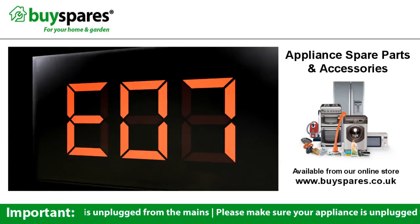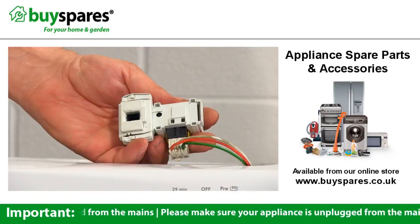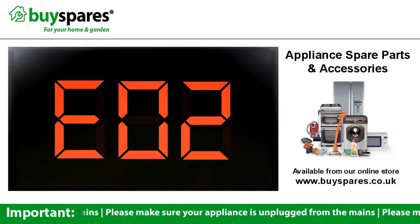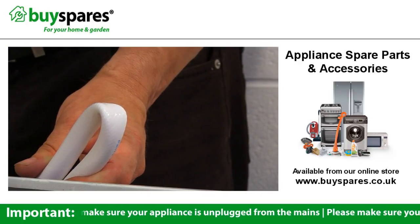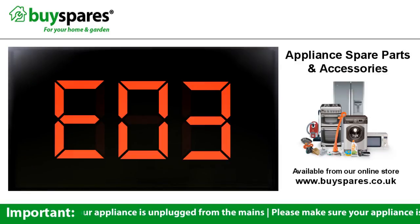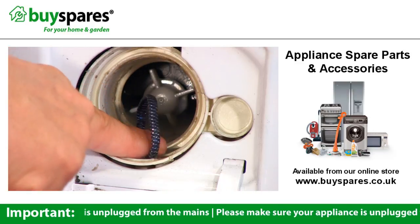E01 or E07 indicates a problem in the door lock area. This could be the door lock, wiring, or PCB. E02 indicates a problem with the fill and can be caused by a pinched supply hose or the water turned off. E03 indicates a problem in the drain circuit, usually caused by debris in the pump.